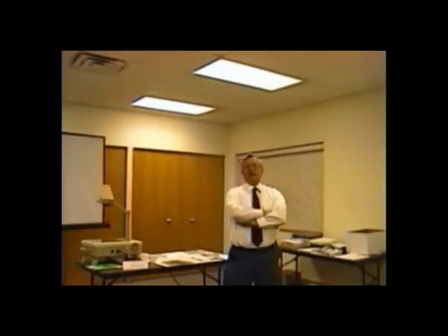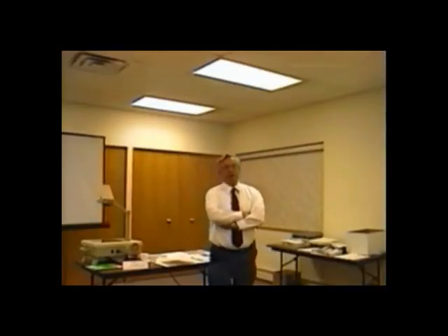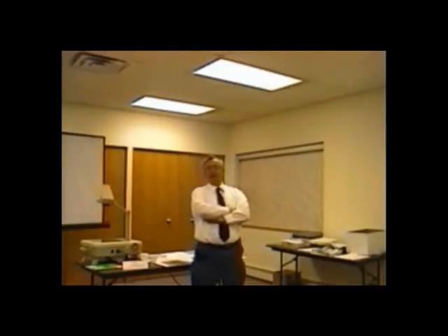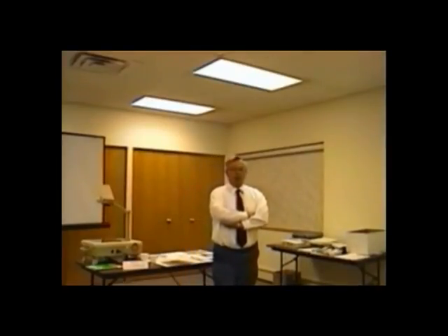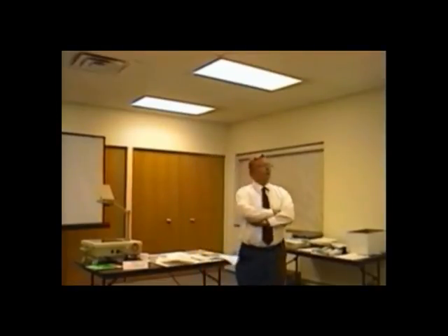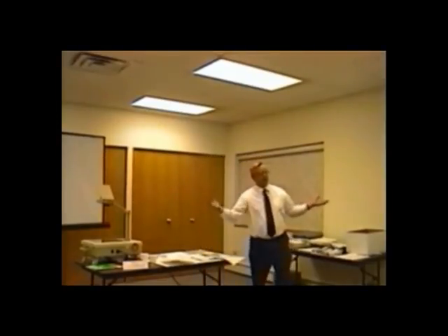Because the fact is, ladies and gentlemen, with R410A all the rules are identical. They're the same. The only thing you have to worry about is that all the pressures are 60% higher. All you do is plug in higher numbers. You have to have R410A equipment, a recovery manifold, and that would be about it. Of course, your dryers today are for 410A. But all the service procedures, superheat, subcooling, everything that we talked about is the same, but 60% higher. So now you're certified in 410A, right?